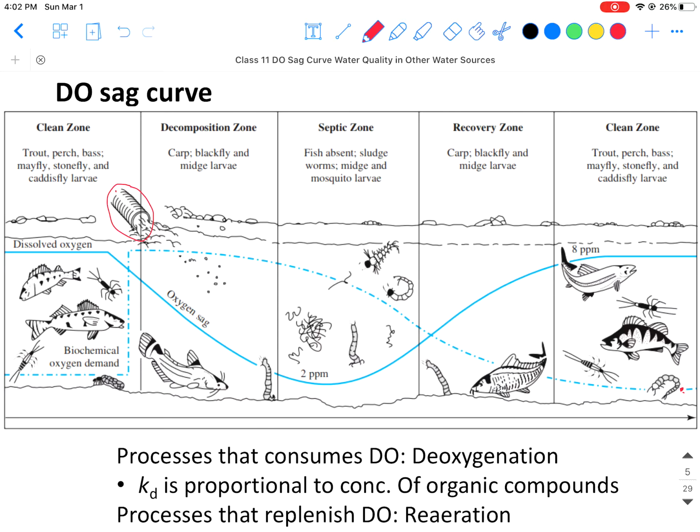And then once this wastewater mixes with the upstream river, that's going to cause a decrease of the dissolved oxygen in the water. And as we have introduced earlier, the lower the dissolved oxygen, the more difficult for these higher level organisms to exist. So this is causing the dissolved oxygen concentration to decrease. And this is because we're oxidizing all of these organics in the water.